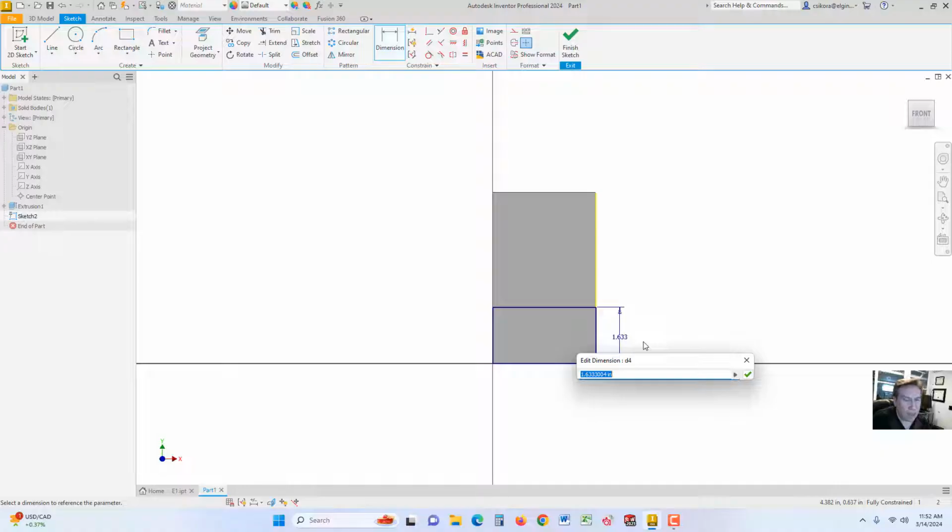Okay, now we could go ahead and type in 1.5. And again, notice I did not backspace over that, just typed in 1.5. Then you could hit the green check or the enter key, and it goes to that dimension. So the height is there. Now notice there is no indicator for the width, and that's because it's locked into the right side. In fact, you could see that yellow line there in mine. Yours might be a different color if you chose a different color for the screen, remember. That's basically just an indicator. It had to create an on-edge relationship, I should say.